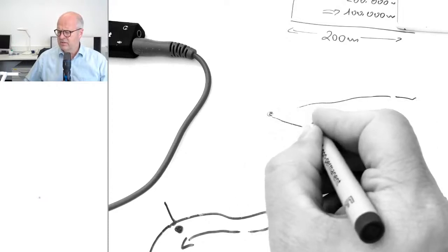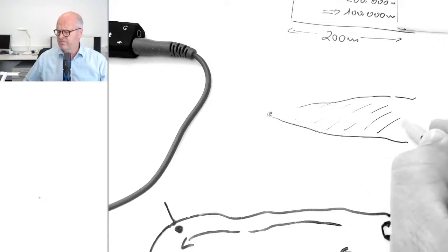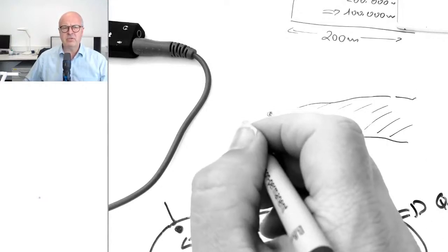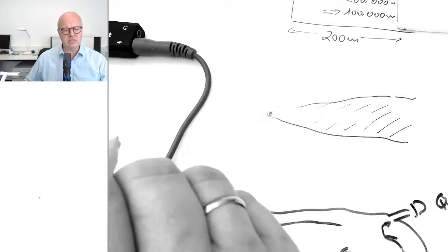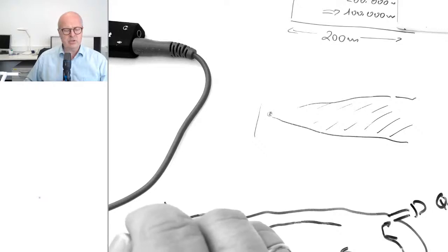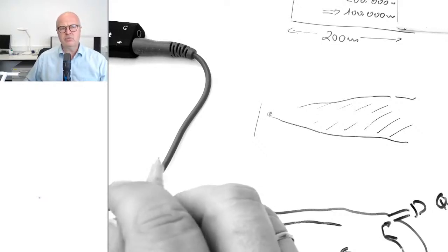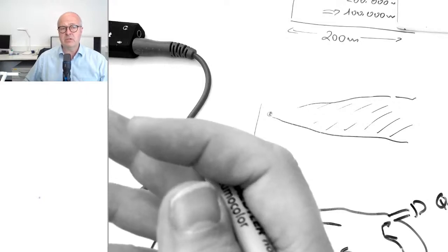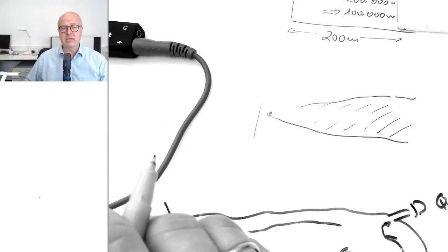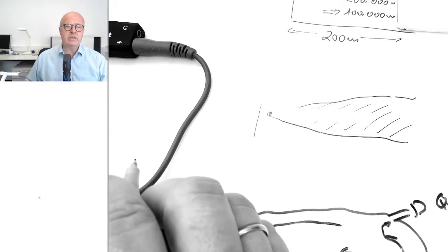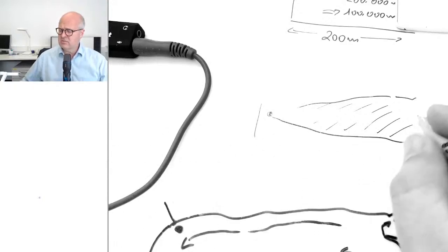So I will already draw an injection plume, and we assume that we have a trace experiment where we inject a tracer into a groundwater and we now measure. And of course, in order to calculate the recovery curve, we need discharge. Discharge can be wrong. We make a wrong assumption about discharge, then we also get a wrong recovery curve.